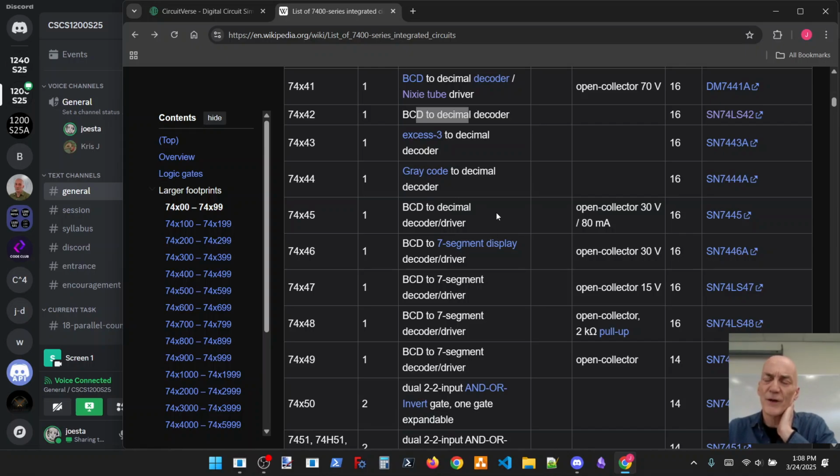Essentially, if we did, it would have been when we were going through the combinations for our latches, because in a latch, when we evaluated it, since the inputs depended upon the previous outputs, that was when we really got the rule that whichever input changes, that's the one we have to evaluate first. And the fact then that, with that propagation delay and so forth, only one input can change at any instant in time.